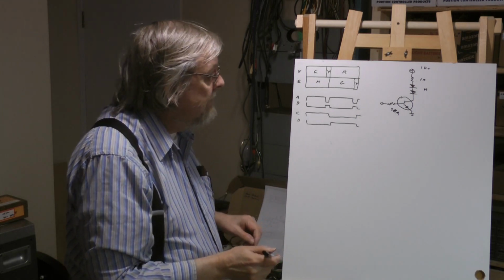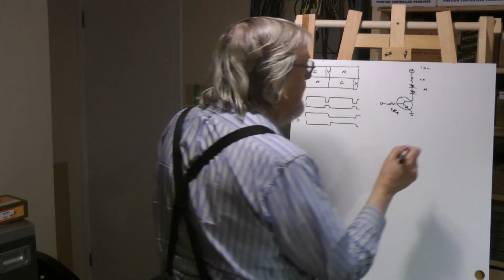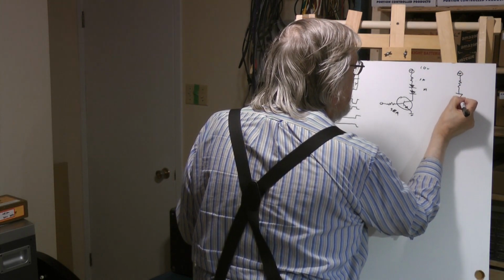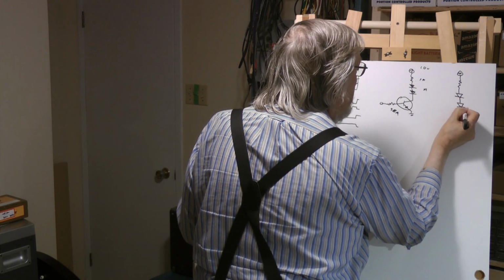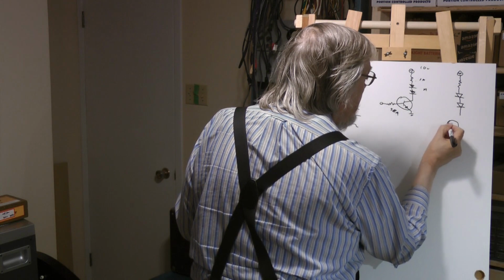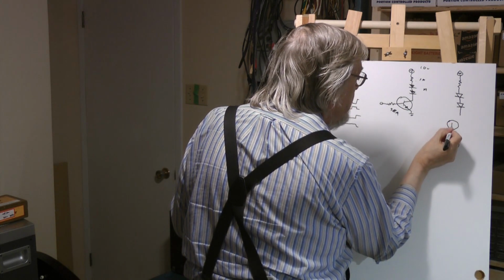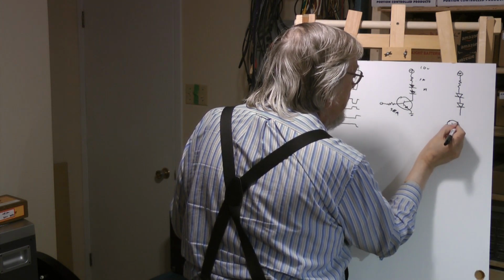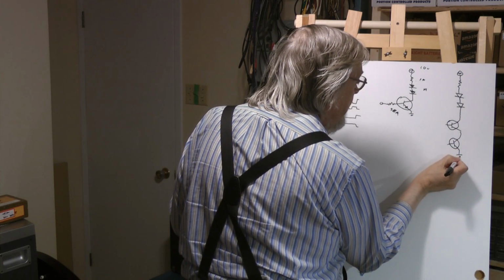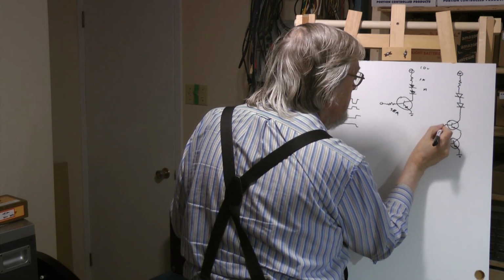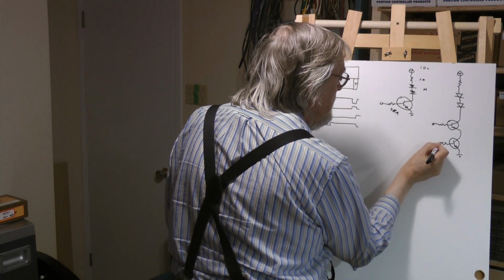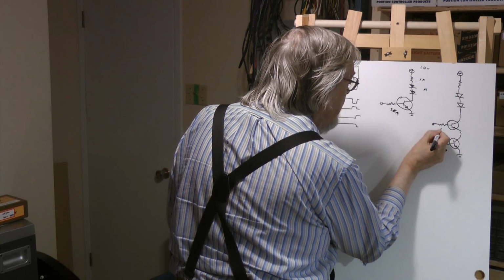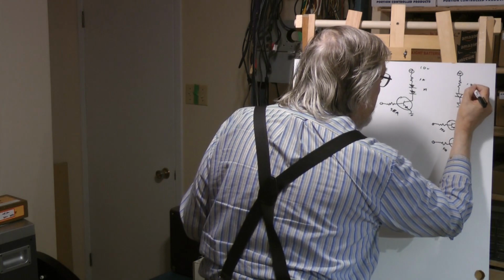Now for the AND gate, that's really easy to do. We just duplicate this, plus a resistor, a couple of diodes, and this time 2 transistors. We're going to get an AND function. Same thing, 56K or so, 1K.